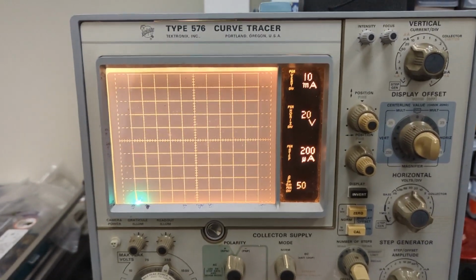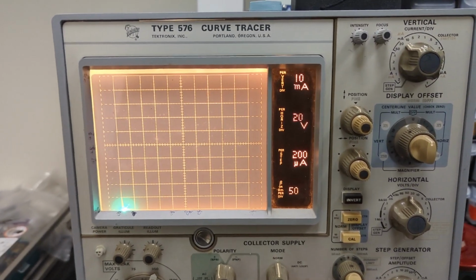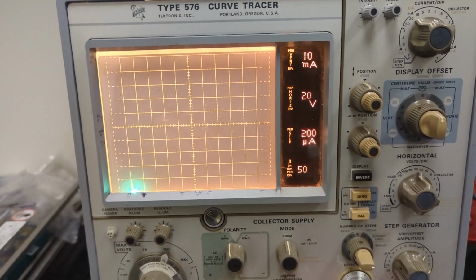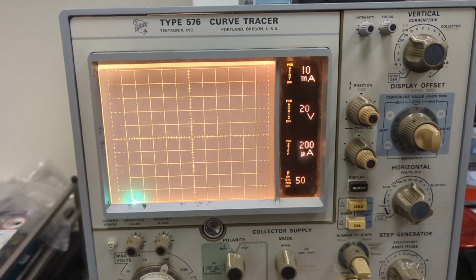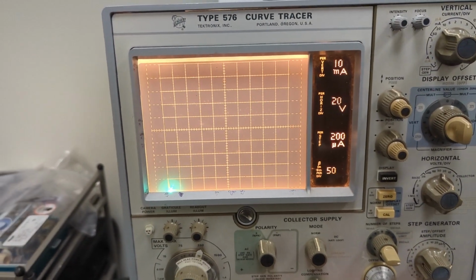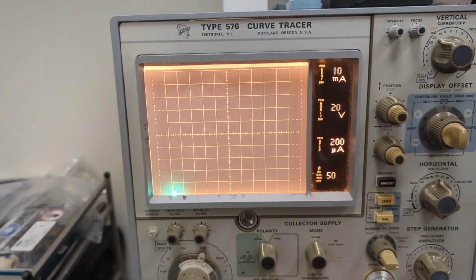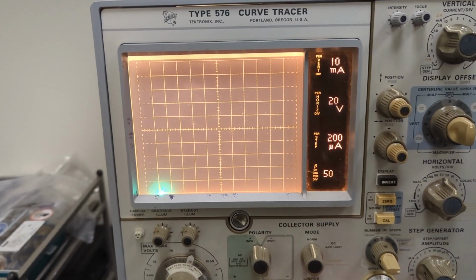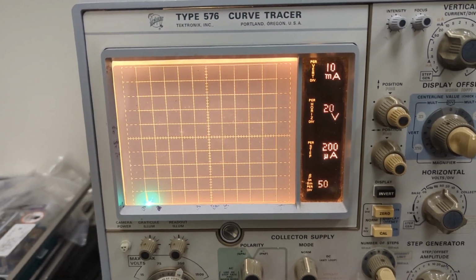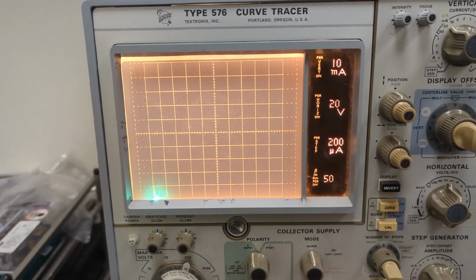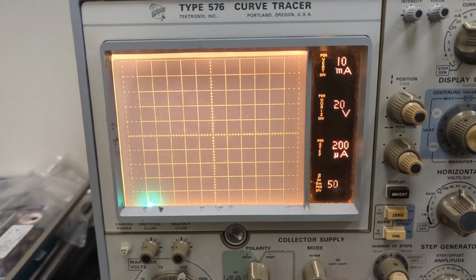So I just wanted to share something I thought was interesting. I was doing some measurements on the A2 board with the unit off, just checking the transistors using the diode test function on my meter. For Q1, which is the series regulator for the 100 volt rail, I wasn't getting any forward bias voltage from base to emitter. They're NPN transistors.